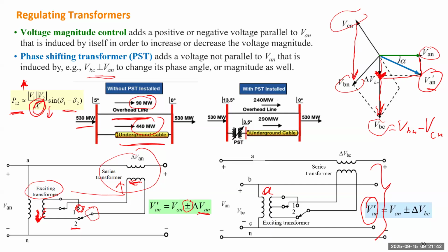Okay, so that's the last thing I want to say about transformers. So next we're ready to move to the next idea, which is the per unit system. Because we introduced the modeling of transformers, and transformers will split the transmission network into many sections of different voltages. So think about you have a generator, which generates electricity, usually not at very high voltage, maybe 35 kV, usually lower than 50 kV. Because you don't want the installation cost with the generator to be too high.